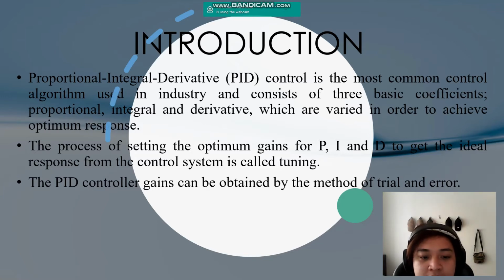In the meantime, they also help to control the maximum overshoot. Only one PID controller will be used for this assignment. The PID controller has optimum control dynamics as well as zero steady state error, fast response and no oscillation, and higher stability where both high starting torque and controlled operating speed are required. The PID simulation can be modeled using MATLAB Simulink to provide accurate PID tuning simulation prior to the device testing.